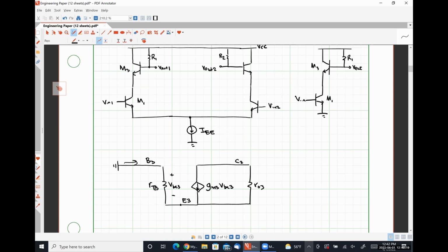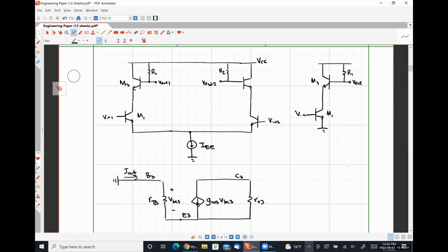Measure the current flowing in the output node, which I'm going to call I out. Now, between our base terminal and ground, we have a resistor R1, but it's grounded on both sides, which is why I'm not drawing it, because it doesn't do anything. Are we okay with that? Because it's grounded, it's at AC ground here because we're doing the short circuit transconductance, and it's at AC ground here, R1 shouldn't show up because it doesn't contribute anything. So it's just there to be confusing. Okay.